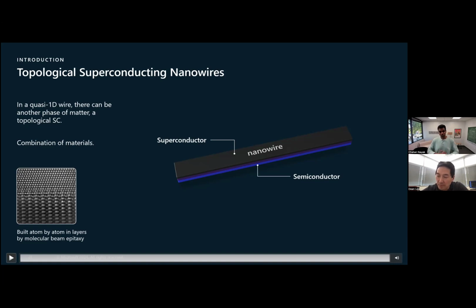It's indium arsenide. It's a different semiconductor. It has applications, for instance, in infrared detectors, like for night vision goggles. But for us, it has other properties that are really nice that we're exploiting here in these nanowires. And what you can see are individual indium and arsenic atoms here. And then on top, it's put into contact with a superconductor, which in this case is aluminum. And you can see the individual aluminum atoms here.